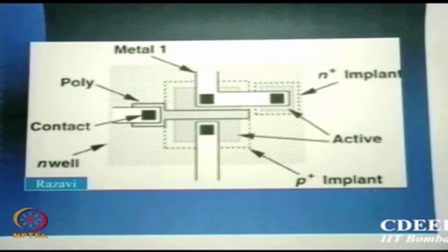Right now you can see there are different directions I am taking the metal out, and that is not acceptable to me. Because if I do this process n number of times, it will show much more variation, unless I am symmetric to something. I will show you what symmetry will give. So this kind of interconnect is not treated well, where you pick up a connection anywhere, anytime and run it anywhere, anytime. It is not a good way of putting your layouts. Okay.